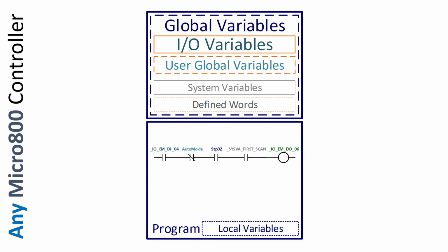And then the 5th instruction is never true or false. As a matter of fact, it's not on or off either. It is just a write instruction that if it's true, it does something, and if it's false, it does something different, just the opposite. Let's consider how these instructions are scanned. Let's take the first one. The first instruction, direct contact, true if on, reads the on-off state of a memory location that it is addressing. If that bit in memory is on, then this instruction is true.